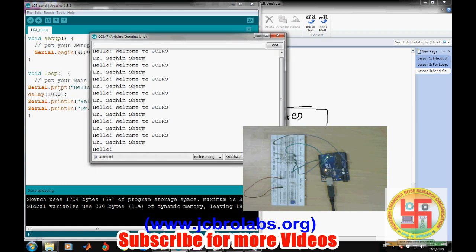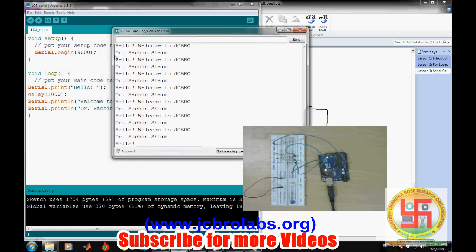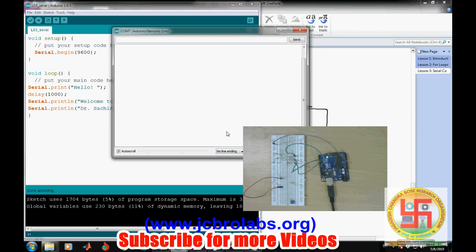So this print command is not adding a new line, it is simply appending the next data to it, while this println is sending a command to move to the next line. Now we have set the serial port at 9600 baud rate, and let's see what happens if we change this baud rate to something else. You will not receive anything.